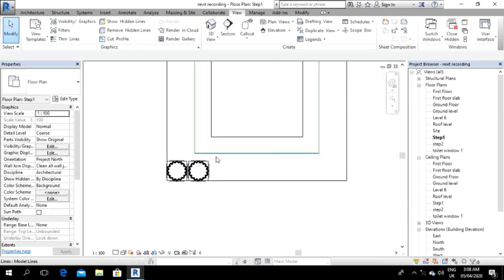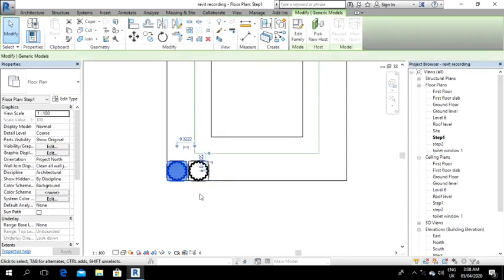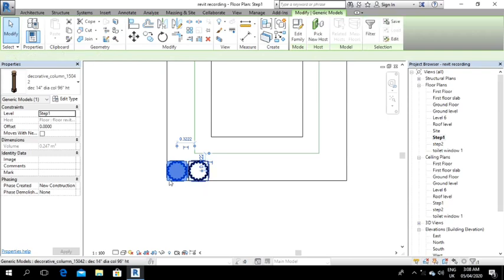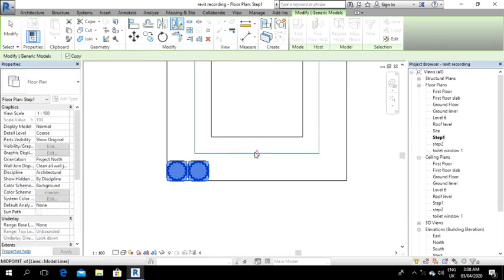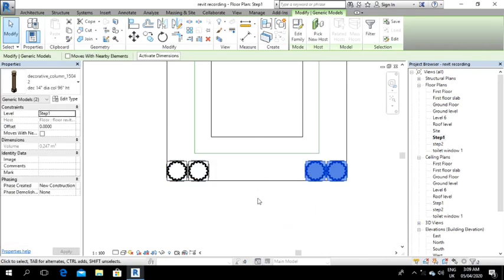Now the next thing is to mirror it to the right. Okay, I don't want to keep placing everything myself, so I'll select this one plus this. Okay, use mirror by draw axis. Use the center of this to draw the axis this way, and it gets placed here by default. Type Ctrl S to save.